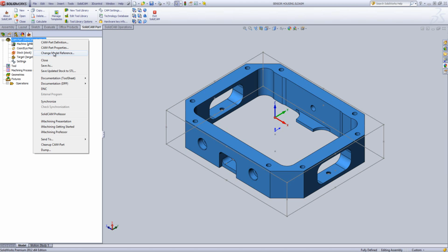the toolpaths into. Close is technically the proper way to close a CAM project. If working in compressed mode, you should always use the close command to properly close the file. Using the close command automatically zips the uncompressed CAM files into a single file, instead of the file and the folder we discussed earlier. This new file will be the name of the project with an extension of PRZ, which is identical to a zip file. You can right-click on the file and extract it with any unzipping program.